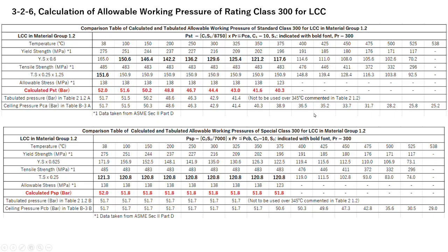This is ASME B16.34. So in case of using valve body material, it cannot be used for LCC material at 350 degree temperature, only 345 degrees Celsius.